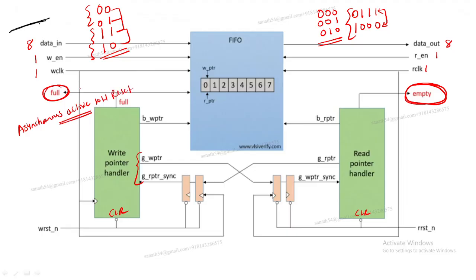That means during the power off, it will be in which state? Reset state. And as I told you, when it is going from reset mode to functional mode, that is synchronous with the clock, and when it is going from functional mode to reset mode, it is asynchronous. Irrespective of the clock, it will reset. Why we need that asynchronous reset is because sometimes my clock will not work.